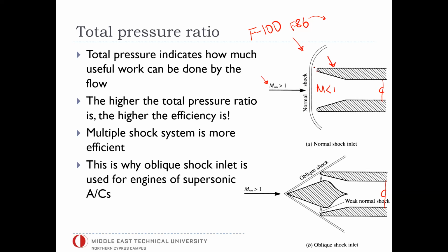It can fly for a limited time only at low supersonic speeds. In that case, what happens is there is either a normal shock wave, a little bit detached, or a normal shock wave attached, but sitting right at the front of the aircraft. Since the freestream Mach number is not that high, with a reasonable reduction in pressure, you can generate a subsonic flow into the engine.